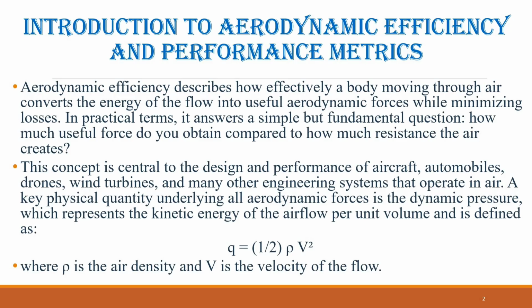that operate in air. A key physical quantity underlying all aerodynamic forces is the dynamic pressure, which represents the kinetic energy of the airflow per unit volume and is defined as dynamic pressure equals 1/2 multiplied by air density multiplied by the square of flow velocity, where ρ is the air density and v is the velocity of the flow.